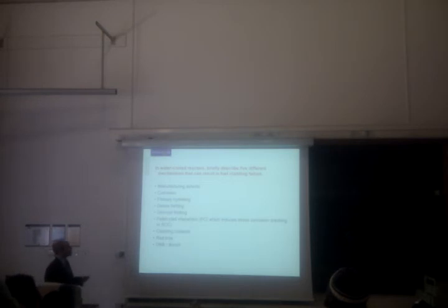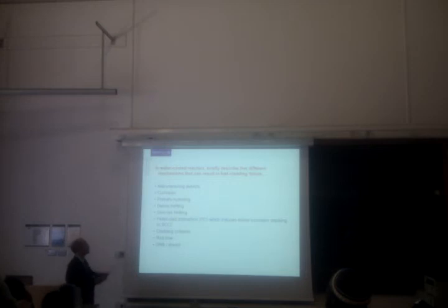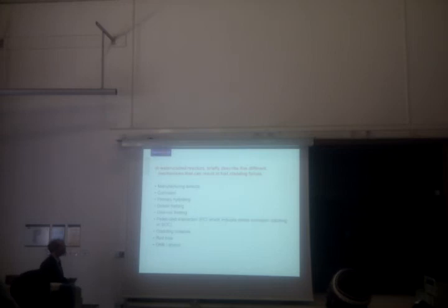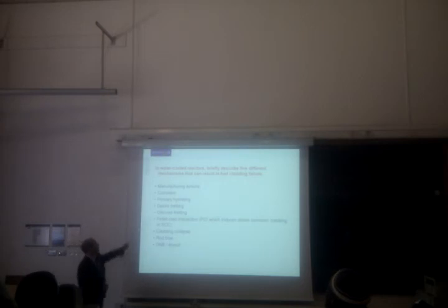How does fuel fail? A whole bunch of different ways, it turns out, some of which are listed there. The question might invite you to describe a number of different ways. It might be 4 or 5 or 6. I've listed rather more than those there. Sometimes we make it wrong. It doesn't happen very often, but we do. Today we make the fuel incorrectly sometimes, so manufacturing defects are a source of error. The cladding will corrode.